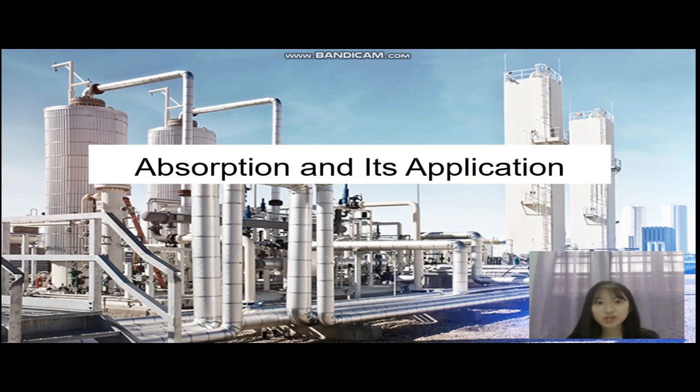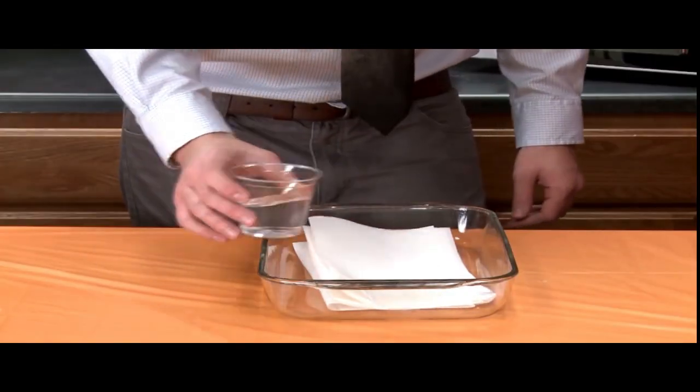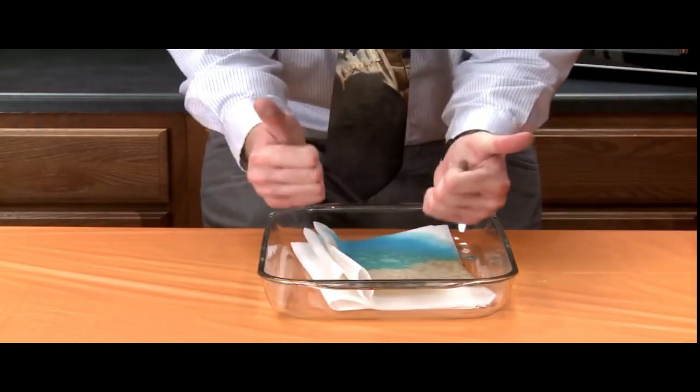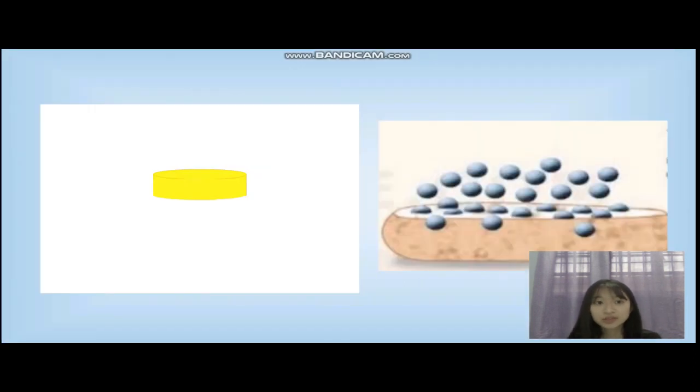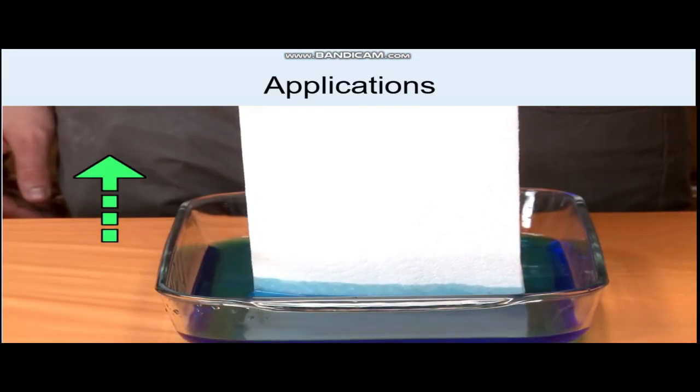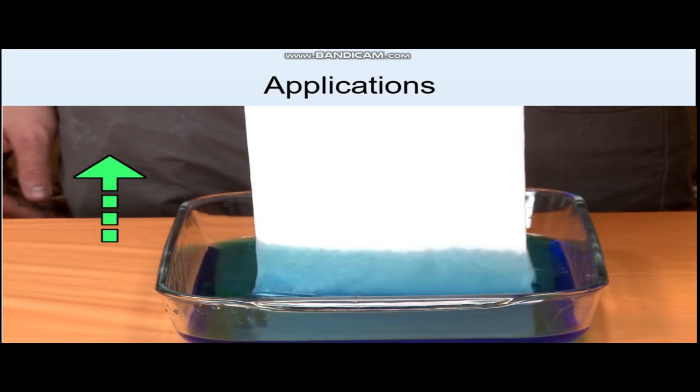Hello everyone, I'm Chang Li Hui and I'm going to talk about absorption and its application. So what is absorption? Absorption is a mass transfer process in which a solute or several solutes from a gas phase is separated by contacting the gas phase with a liquid phase. So during this process, molecules are drawn into the bulk of the phase and liquid phase is immiscible in the gas phase. So here are some applications of the absorption process.